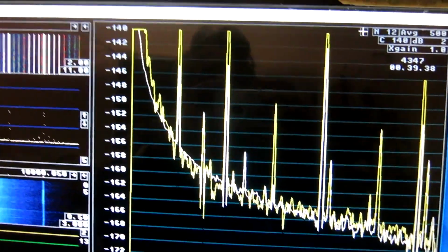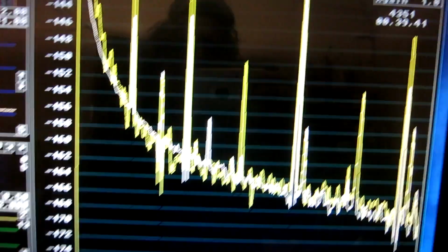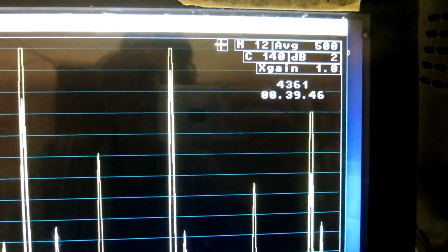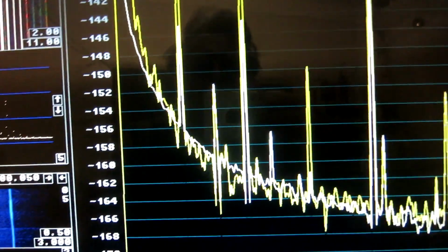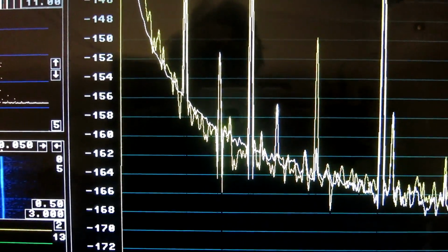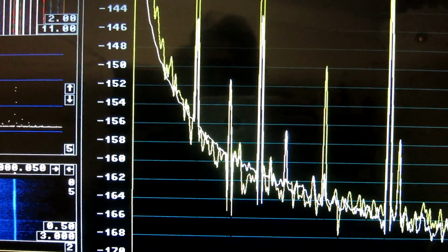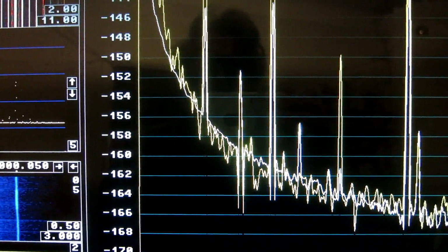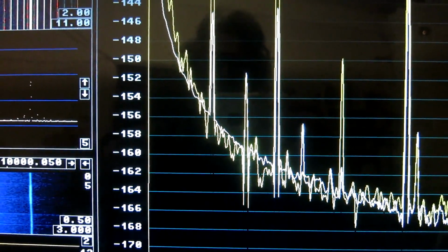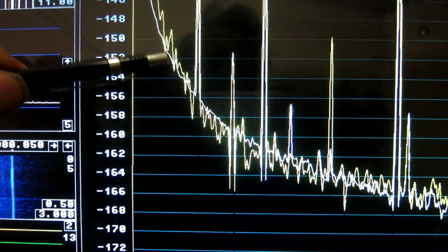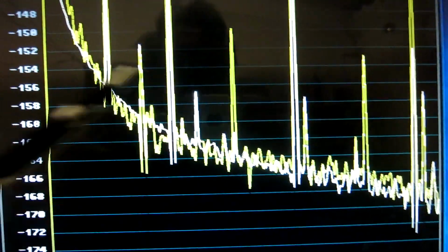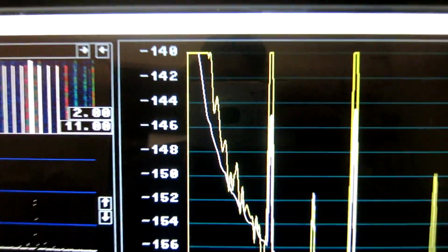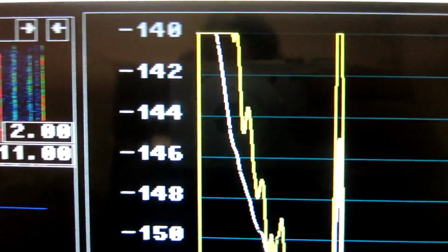Here is the signal analyzer window of Linrad, after 39 minutes of collecting correlation averages. The curves here, the yellow is phase noise, the sum of the real and the imaginary powers. This yellow curve is phase noise, and the white curve here is amplitude noise. And I think colors become more visible when I move the camera.